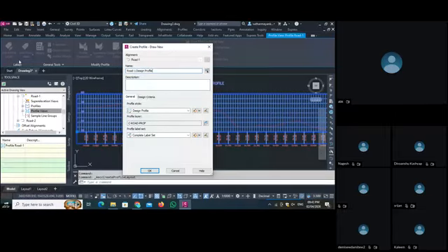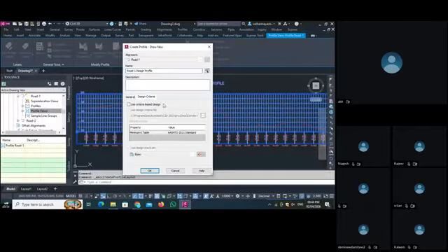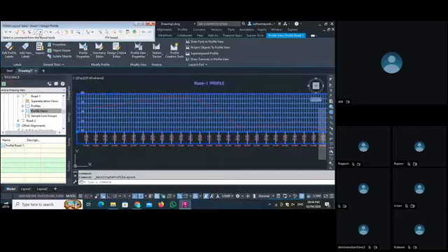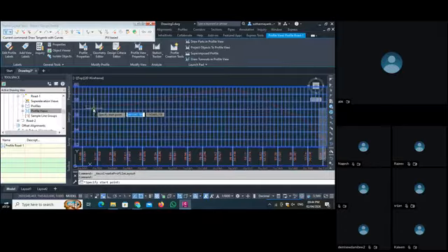You can see the label is now not visible, but when you select your design profile, the label is visible. You can add the label from here also. Now you can set the design check set criteria also. You put OK here. Now again the same menu opens as we saw in the alignment creation tool. So what we do here, we create a design profile by maintaining our grading, our curves, and cut and fill.